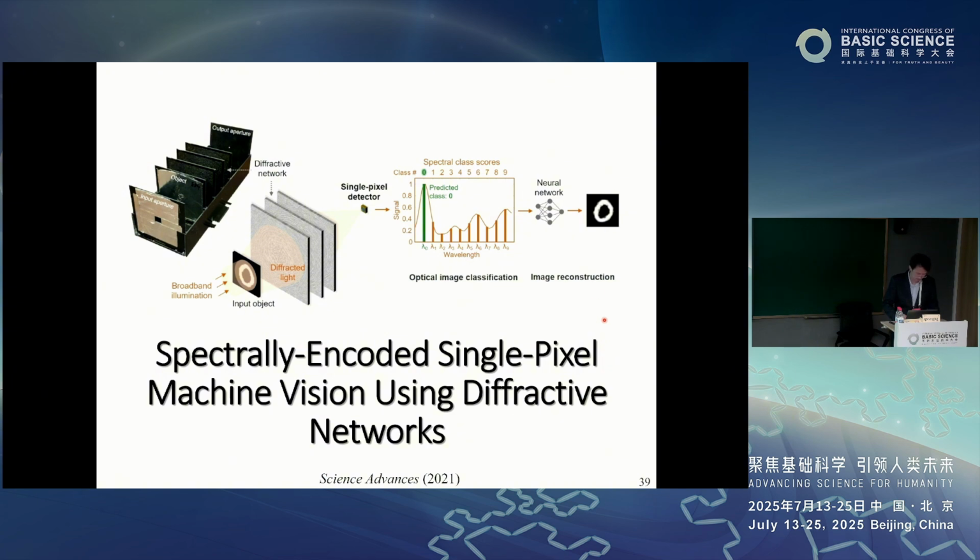The output signal is detected using a lock-in amplifier synchronized with mixers and amplifier chains. This setup enables selective coherent detection of modulated terahertz signals.